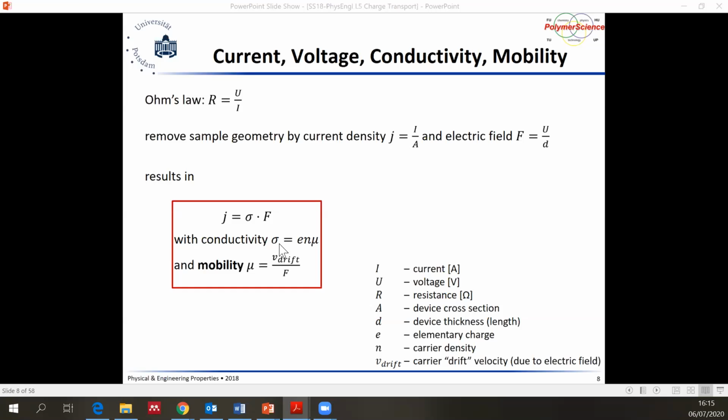So even though the equation sigma equals e N mu is written here so neatly, one has to write in brackets that sigma itself is dependent on N naught, which is the carrier density in equilibrium, the electric field, light intensity, temperature, and the band gap. So it has many dependencies. But at this stage, don't worry about that. For now, just learn that sigma equals e N mu.